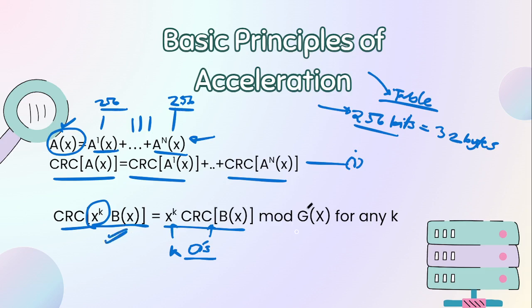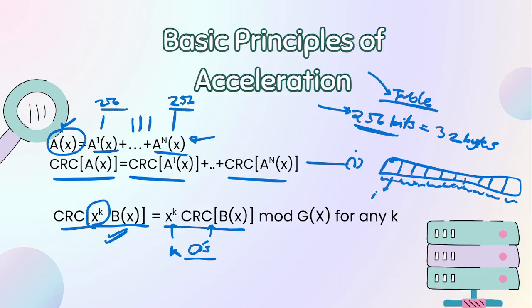So given that you have a 256-bit word, let's say your word is a very large long word, so you break it into bytes, or even bigger, let's say 4 bytes or whatever. You'll see different approaches being used. In my case, I prefer bytes because tables are easy to make over bytes, right? Because each table is 256 deep and not gigantic. So that's what I do. Now it's a sum. Let's say this was A1x, this byte was A2x, and so on till ANX. These are what is shown here.